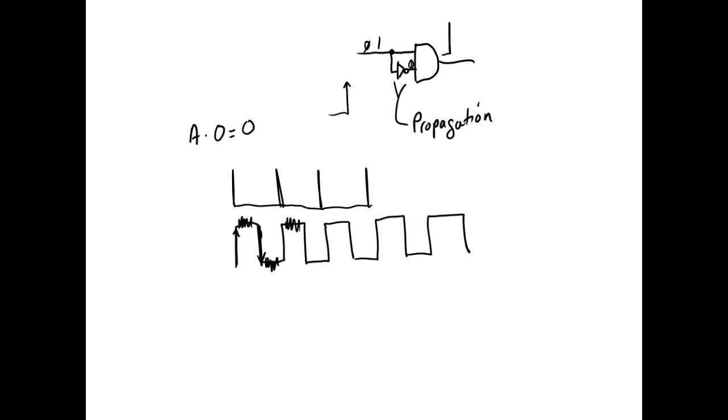And we can do this. The problem is I'd have to get my high-speed scope. The scope I'm using only has a bandwidth of 25 megahertz. So what I've done is, and it's got to be an odd number of inverters, because if you put an even number, you end up with the same. If you put an odd number, you end up with what? Inversion.